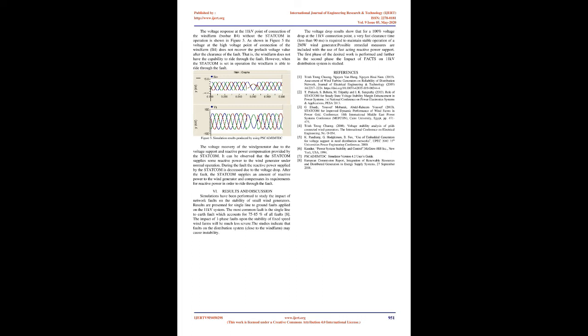B. Simulation. Many studies have been conducted on wind turbines connected to 11 kV networks and have published several results. However, very few studies have been conducted on the reticulation regions. The 5-bus system was adopted. It was used to demonstrate the effects of wind turbines and to understand the concept of embedded generation. The Statcom is a 2-level VSC with voltage space vector PWM control. A conventional PI controller has been used to control the reactive power output of the Statcom.